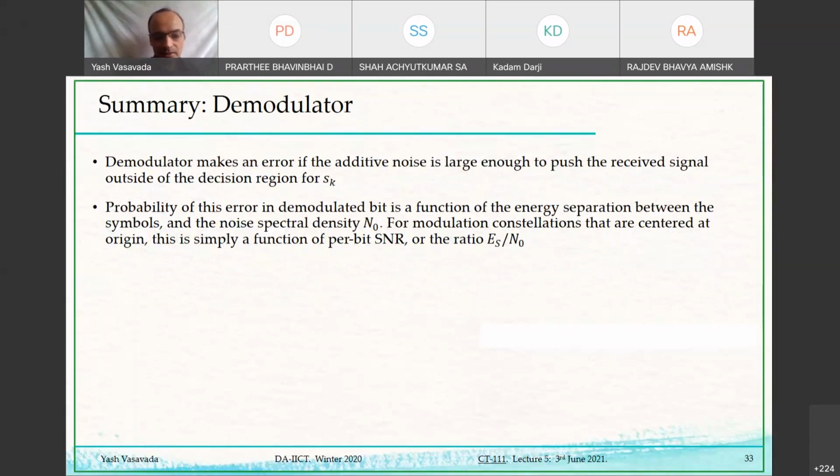In the example that I gave you, we were making detection errors. We couldn't decode the medicine in that prescription. That is not the luxury that a demodulator has. The demodulator will detect a symbol and it doesn't know whether that detection is right or wrong. But if the detection is wrong, then the sequence of log base 2 of M bits that the demodulator produces are going to be wrong. They are not going to be the same bits that the modulator has sent.